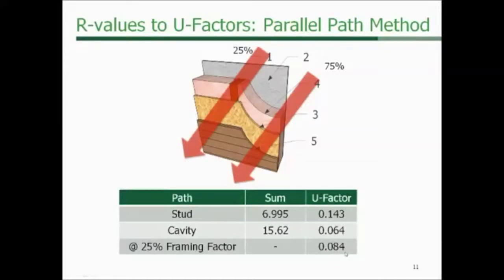Okay, so there's certain numbers that I'd like you guys to remember during this presentation, and this is one of them, 0.084. So this was an R13 wall with 2x4 studs, and that has a U factor of 0.084. So remember 0.084 for me during the presentation. We'll come back to it. That's just showing the math of how we got there.